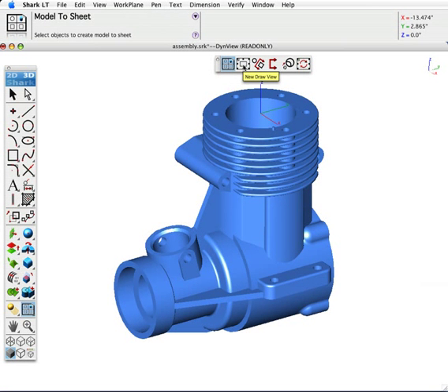The second icon is to manually create drawing views. This is like a view that sets the view orientation to side, top, front, isometric, trimetric. Auxiliary views, section views, detail views, and regenerating draw views. All the draw views are associative to the 3D parts, such that if changes are made in the 3D part, they will reflect back into the 2D drawing.